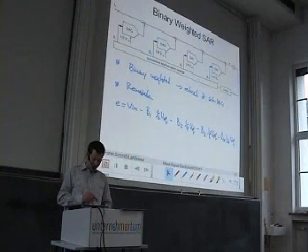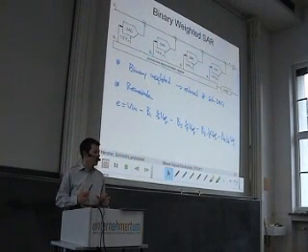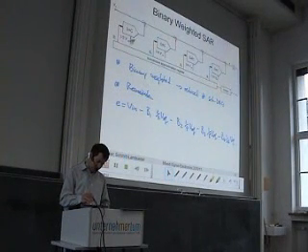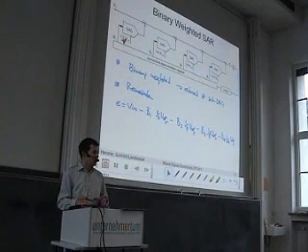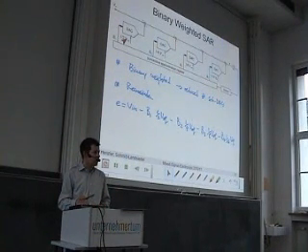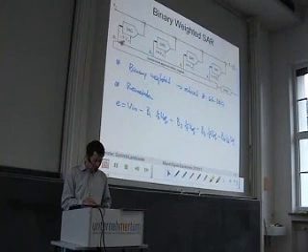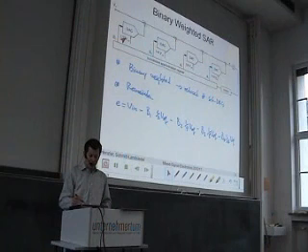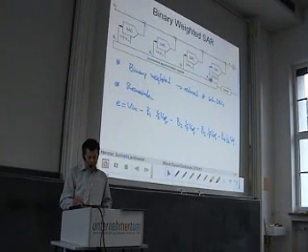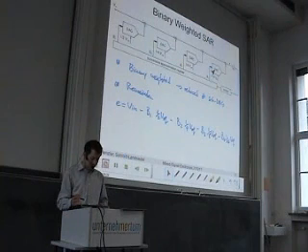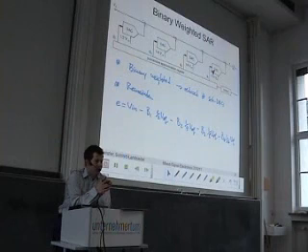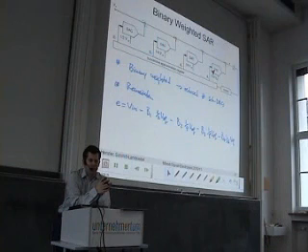Interesting here is that the error contribution also scales with the weighting factors. So it is good to note here that the MSB DAC has the strongest matching requirements, because due to this highest reference voltage here, its error contributes the most. And the more you go towards the LSB, the less is the error contribution. So if your task would be to build such a device, what do you think is the main disadvantage that we have here?